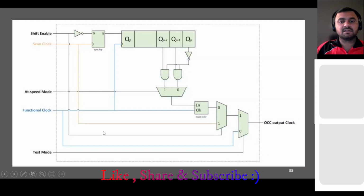But suppose this scan enable goes low, that means you are in the functional path now. Then this logic will come into the picture, and this at-speed mode will be 1 here, and then based on 1 or 0, based on the number of pulses you need, this OCC output clock will be generated. In the waveform, you will easily see how many clocks and how much data there are. So this is another kind of instrument you can say. This is the clock controller.